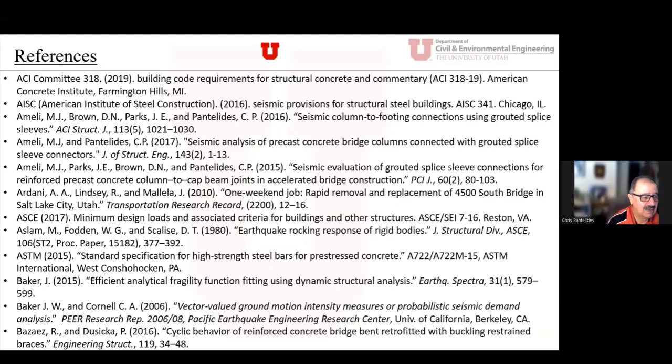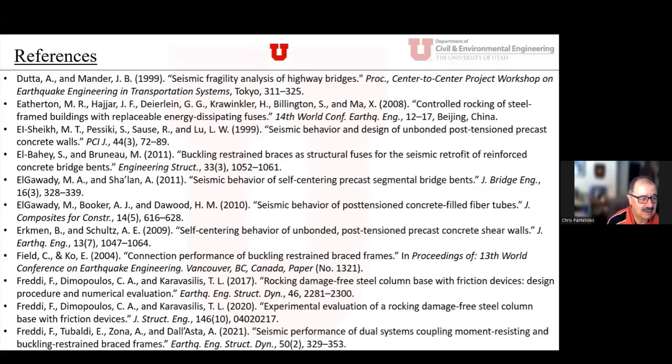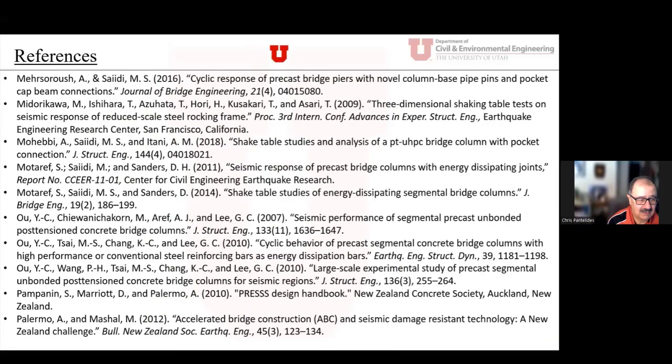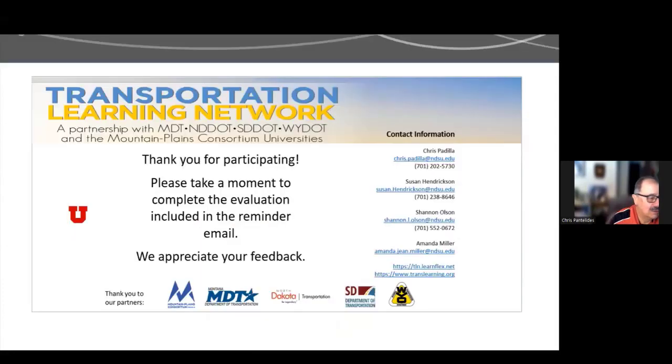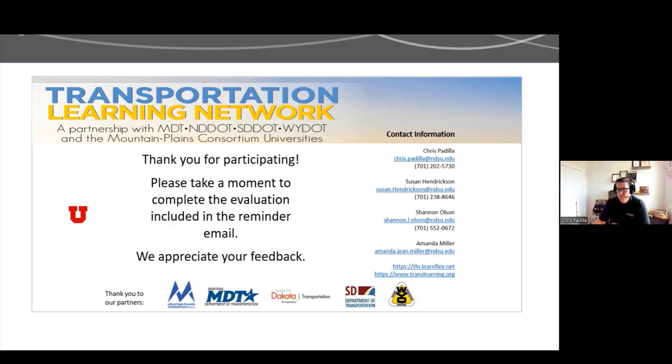Okay, why such a shallow spacing for the spiral ties? So this is an experiment done in the laboratory, and we want to make sure, of course, that we don't have any unexpected results with our columns. And to be fair, we had asked for number 4 spirals, but the delivery came as number 5, so we took it. Of course, in the field, you would have a different spacing.